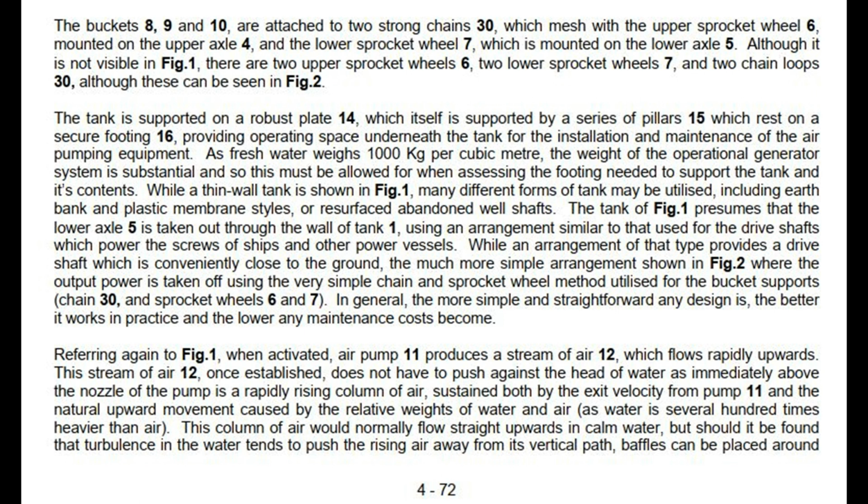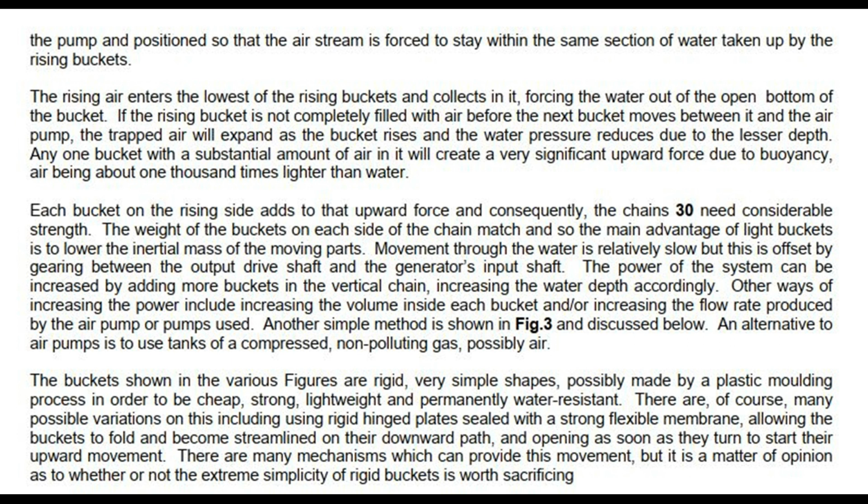This column of air would normally flow straight upwards in calm water, but should it be found that turbulence in the water tends to push the rising air away from its vertical path, baffles can be placed around the pump and positioned so that the air stream is forced to stay within the same section of water taken up by the rising buckets. The rising air enters the lowest of the rising buckets and collects in it, forcing the water out of the open bottom of the bucket.